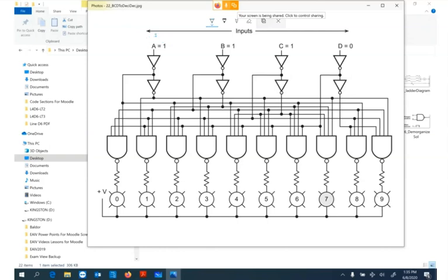if you think of binary counting, 1, 2, 4, 8, and of course with a 1 in each of those digits, that adds up to 7. Now the trick of following this through is, let's just look at number 8. With a 0 here, we have a 1 here. With a 1 on the input to this inverter gate, that means this will be a 0. So anything connected to that would be a 0. So remember we need all 1s to make the output of this a 0.